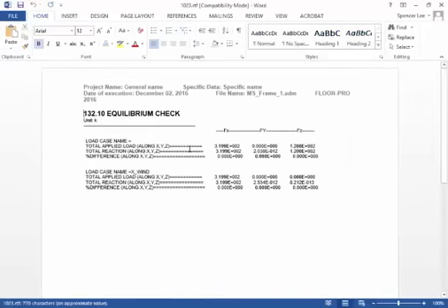So we have 40 kips times 2 at either side from the line load, so that's 80 kips plus an additional 80 kips, so there should be around 160 kips of applied load on this structure. Let's see, we have 320 for FX. This is shown right here, so I'm off just a little bit.